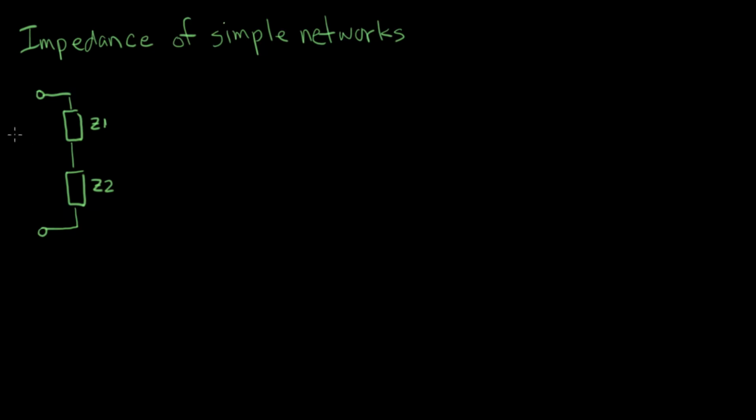When we talk about impedance, what we mean is we take sinusoidal signals. We take a sinusoidal voltage and divide it by a sinusoidal current. And that ratio is impedance. And so the voltage is impressed across the two terminals here. And then the current I flows this way. So this will be I, and this will be plus or minus V between here and here. And the relationship between those two things is called impedance.